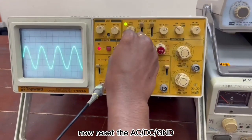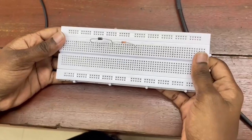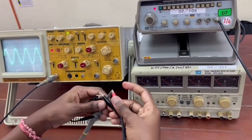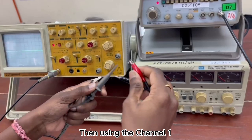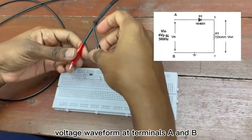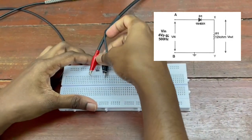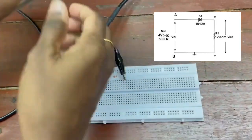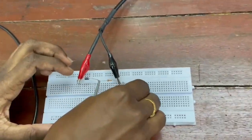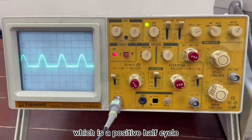Now reset the AC or DC or GND switch of the oscilloscope to the DC position. Then, using channel 1, measure the input voltage waveform at terminals A and B. This is the half-wave rectifier circuit waveform that we got, which is a positive half cycle.